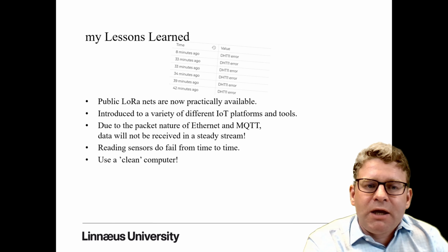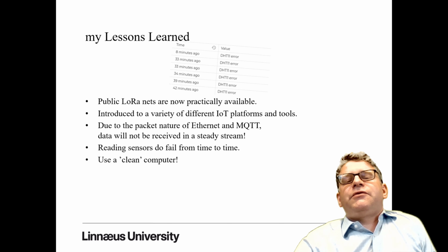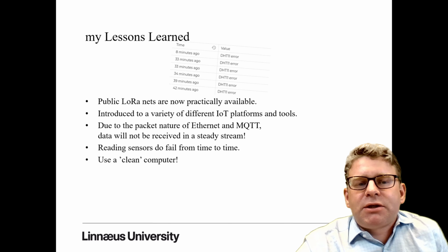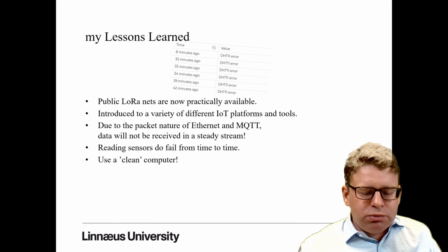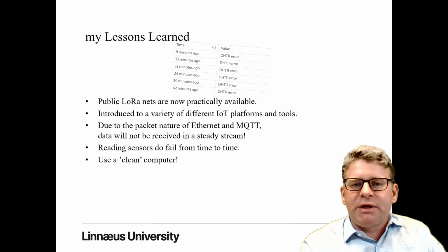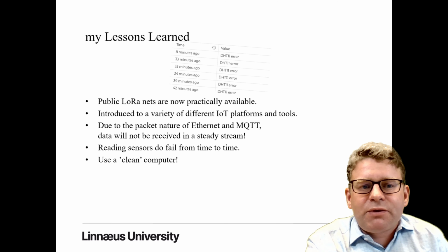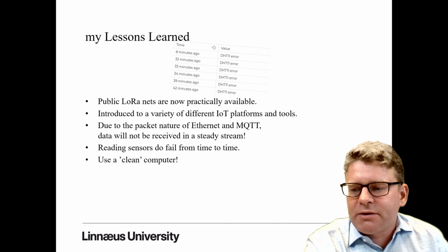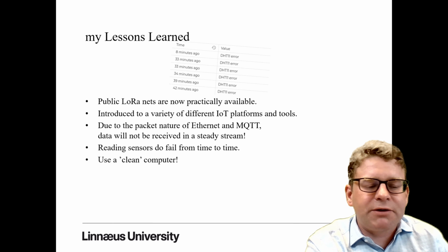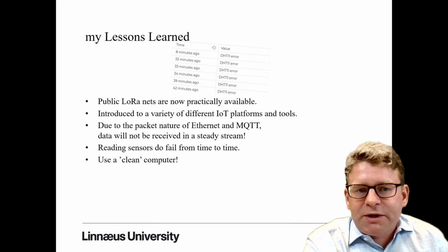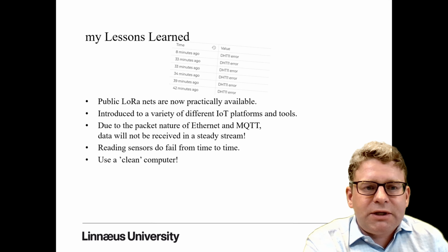And well, one interesting thing was that packages of MQTT data are not received within the same time. They are received quite unsteadily. It can be some 20 seconds between one and then 30 seconds to the next one or so, due to the packet nature of Ethernet and MQTT.